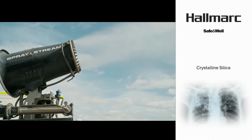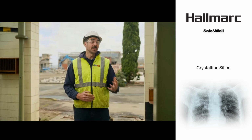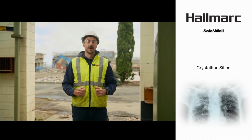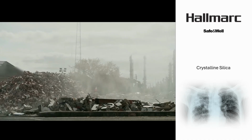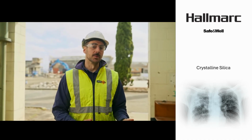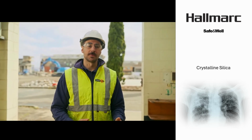Fogging cannons or foggers are often portable and work best when they are placed upwind of that work area. Fixed misting systems work best when they surround a work area. The ultrafine mist acts like a curtain of water, preventing the spread of airborne dust. Where fixed or portable dust suppression systems aren't suitable, misting nozzles can also be attached to handheld hoses.